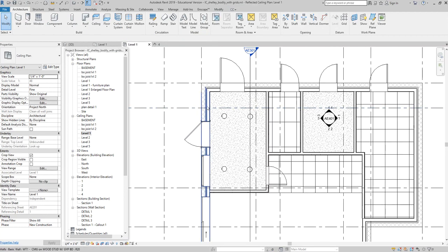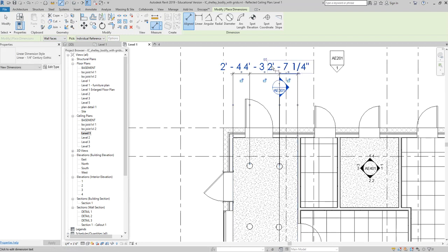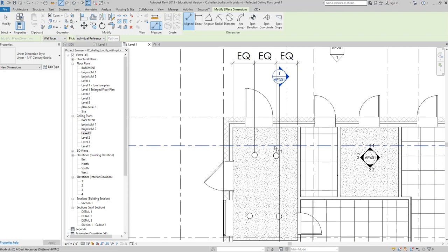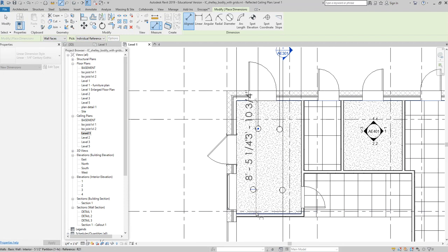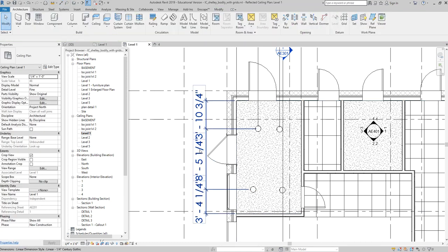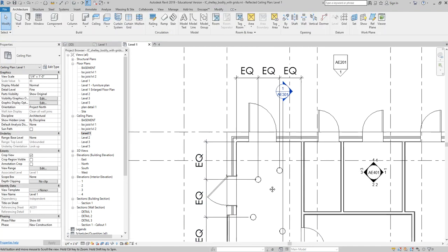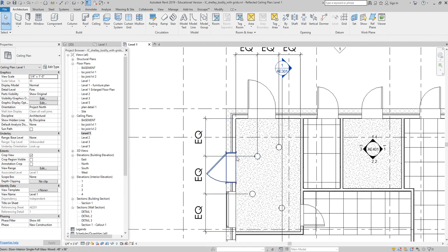And if I want those lights to be equally spaced in this room, dimension, DI, and I can grab the center point, go to the next wall, pull it up, equal, click, and they're equal, right? DI, dimension, here we go. And although I love this functionality, I get super bored doing it all the time, right? Because I'm actually adding quite a few dimensions that I don't really need, you know? Okay, so that looks pretty good. It's equally spaced from here to here to here. It's equally spaced from here to here to here.